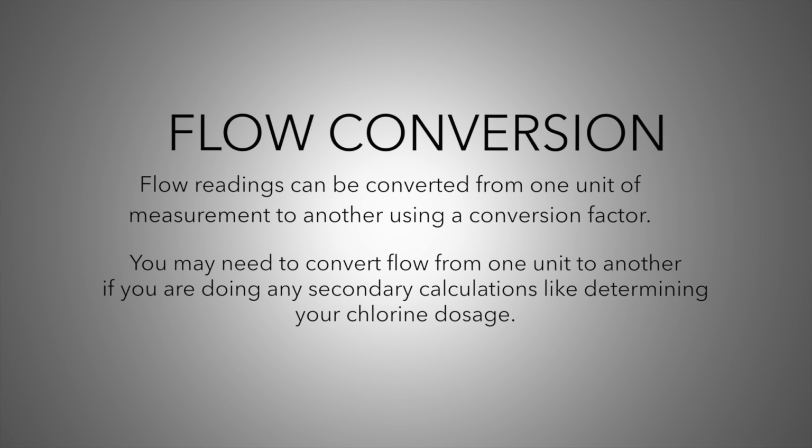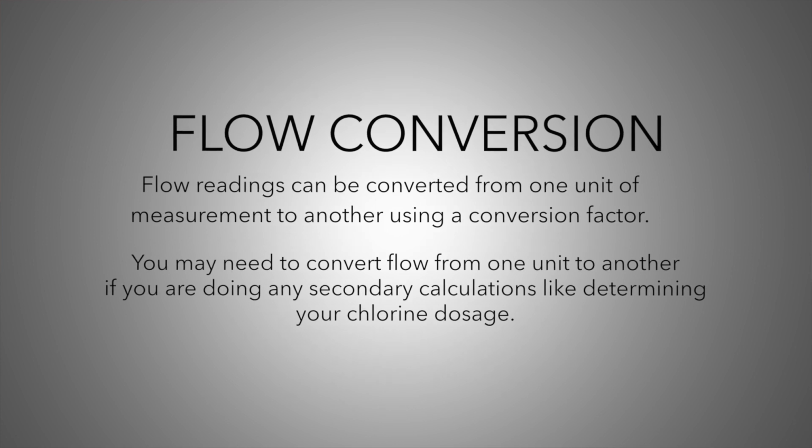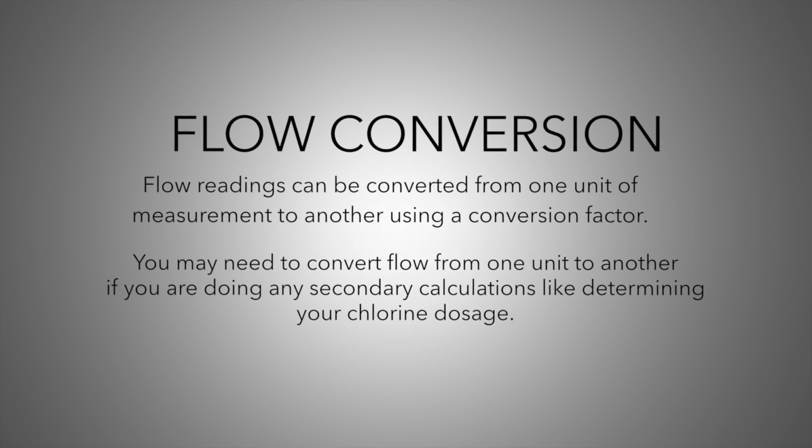Flow readings can be converted from one unit of measurement to another using a conversion factor. You may need to convert flow from one unit to another if you are doing any secondary calculations, like determining your chlorine dosage. Always note the unit of measurement from your flow meter.